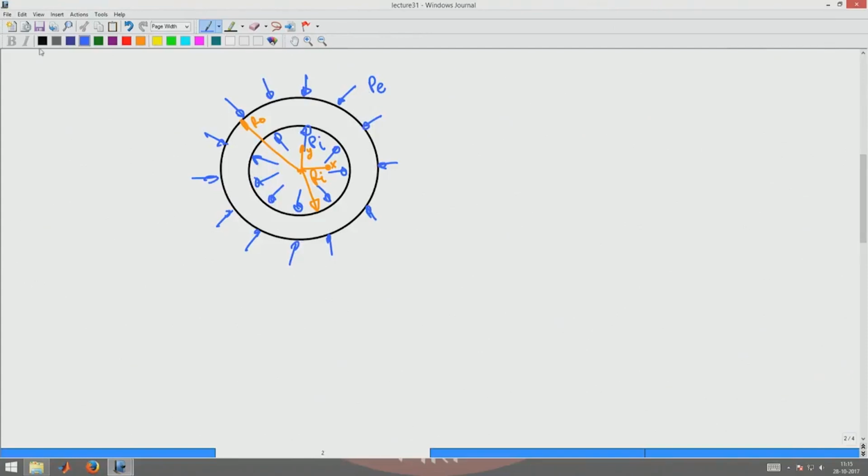So, the boundary conditions now will be sigma rr at r equal to Ri is equal to minus Pi, same as what we saw in the last lecture, and sigma rr at r equal to R naught, instead of being 0, is now going to be minus P external.